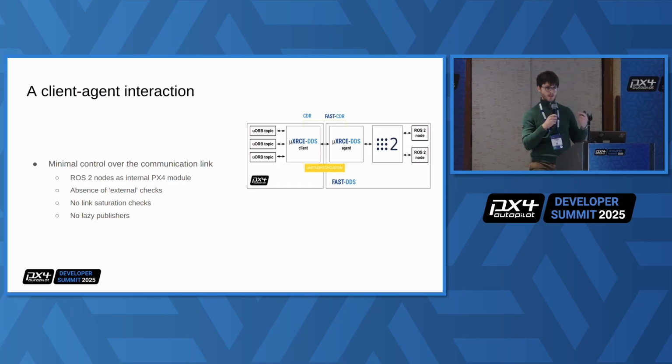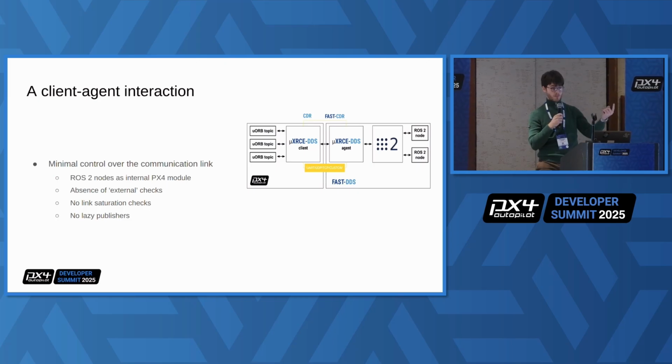For example, if you try to send a MAVLink vehicle command and you do a force arm, and if you dig into the commander, there is code for forcing arm, the same as when you do vehicle_command arm -f on the NuttX shell, it will be rejected because it's being considered as coming from an external module, so you cannot externally force arm.